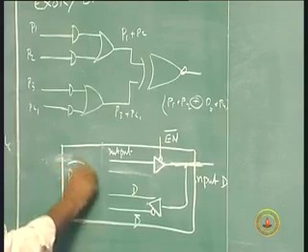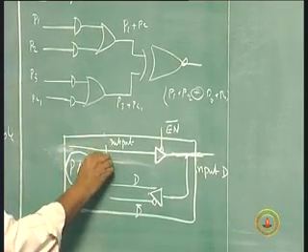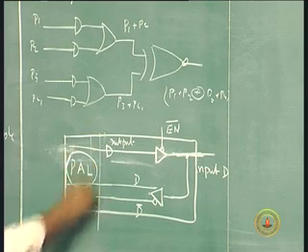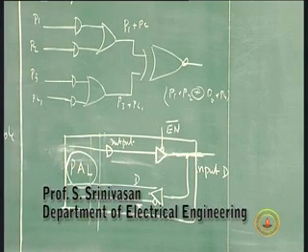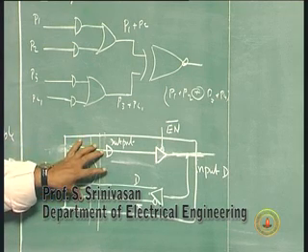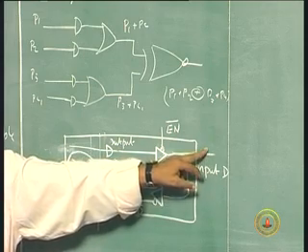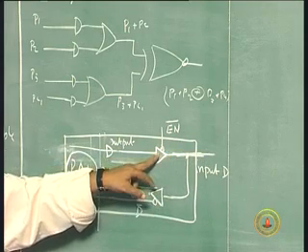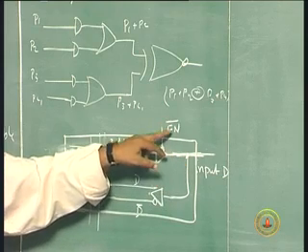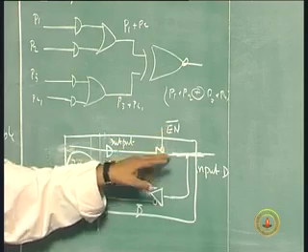This is the rest of the circuitry. So, because this will come from a combination of AND gates, and this will go as inputs for all that type of thing. So, the total thing is a PIL. What we had originally, normally I would have had this output available to you. Now, I am putting this extra logic here, which can keep it as an output if you want by making En equal to 0. If you do not want this to be an output, I make En is 1 and this is disconnected.